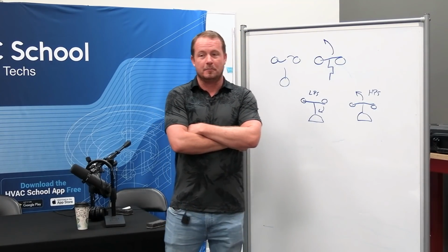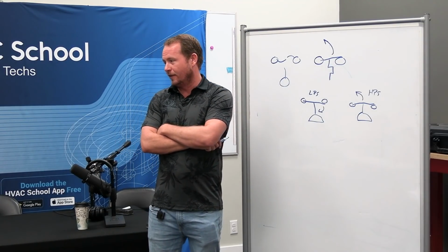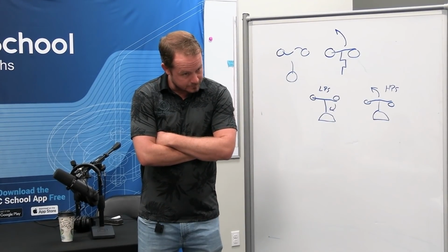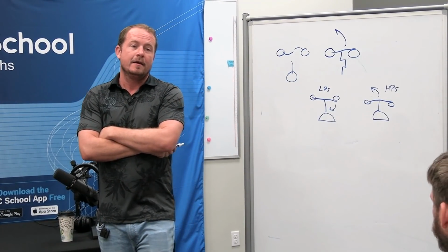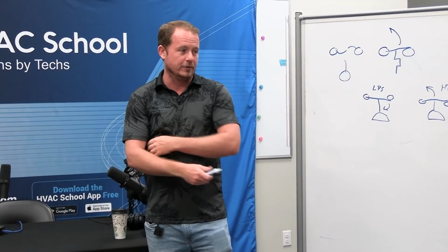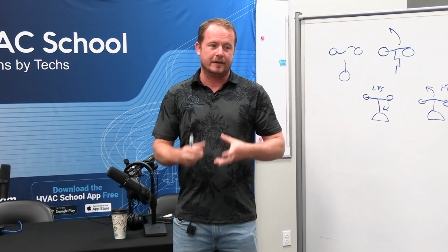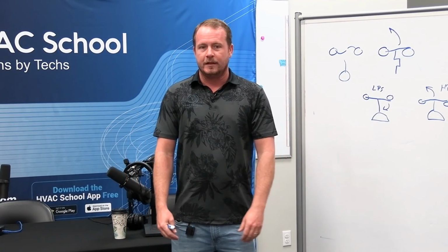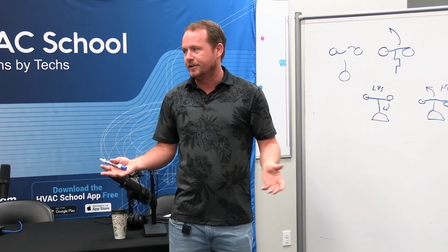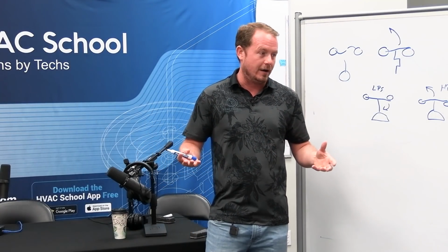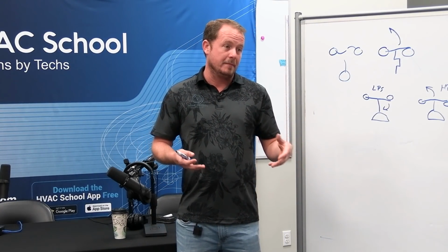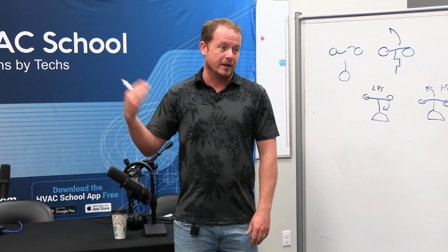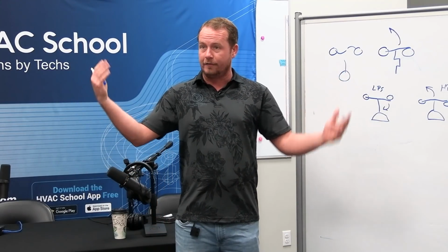Now, on Lennox, the most likely cause of a high pressure switch lockout trip on those Lennox heat pumps? Condenser fan. Right, because a lot of those condenser fans are those older clamshell condenser fans that just don't last as long. They'll intermittently work for a while, then overheat and shut off. And if the condenser fan shuts off, the compressor may overheat, but it may just keep going out, and likely will keep going out on head pressure until that thing trips enough that it locks out, and you show up, turn it back on, and everything works.